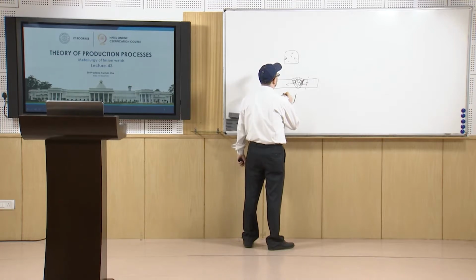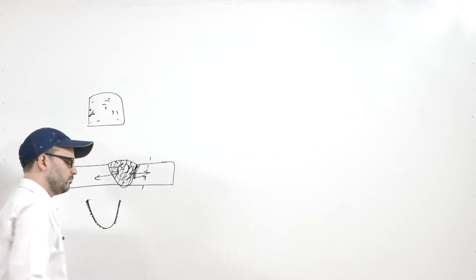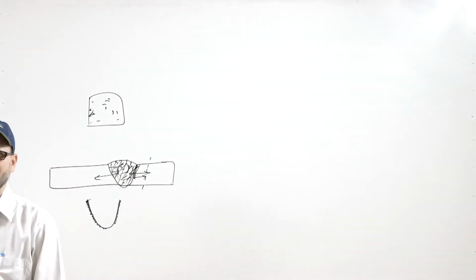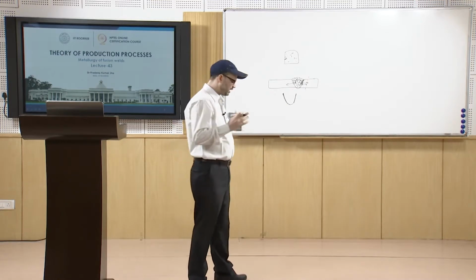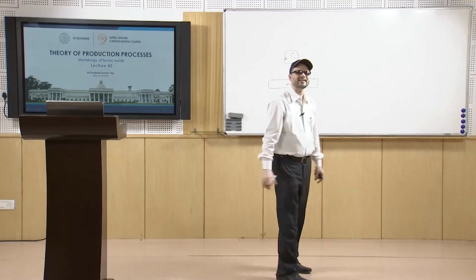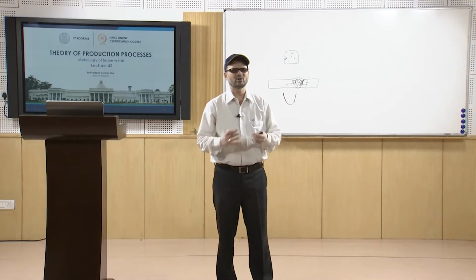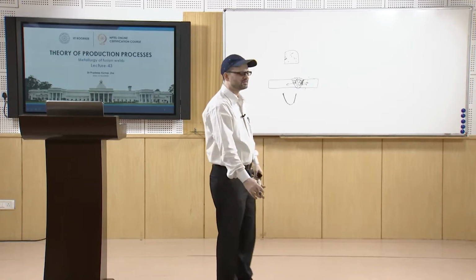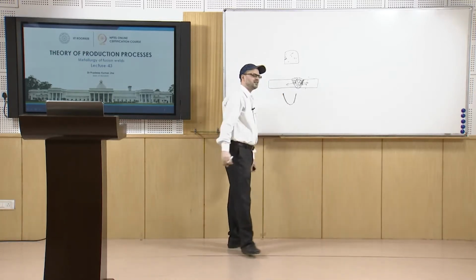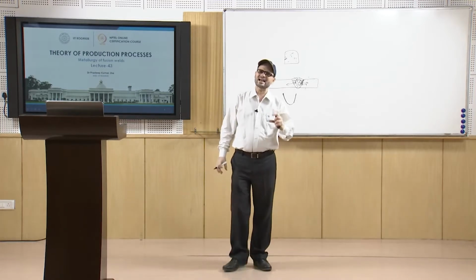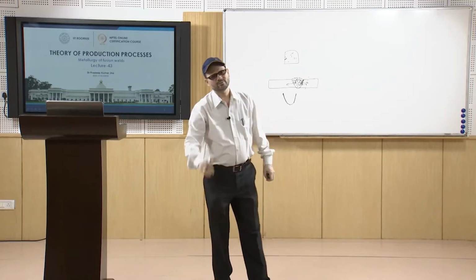So, you will have the presence of these as the existing nuclei, and then from there the growth starts. The nucleation barrier which is there in the case of normal solidification is not the case here, because you have heterogeneous nucleation sites, and these unmelted, partly melted grains act as the nucleation centers, and from there the solidification starts.